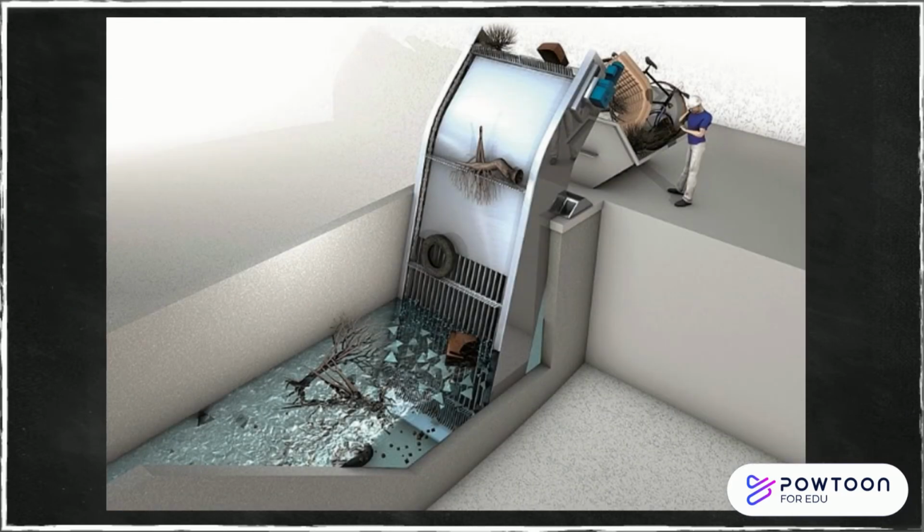So treatment begins with a bar rack, and this is what a typical bar rack looks like. It removes large items such as twigs and larger trash items like plastic bottles, anything that's in the water that shouldn't be. The bar rack is cleaned often so that water may flow through unfettered. In a large municipal water treatment plant, this is an automated process. So using a step or ladder moving screen dumps the debris and lets water flow through. Some bar racks have a mechanical arm which pushes the debris off to let the water pass through.